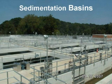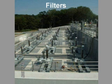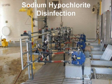This is one of the treatment facilities, the 85 MGD facility. It is not online yet. Both of the treatment facilities, the one on the east side and the west side, are about the same. They include drum screenings again from the tunnel flow, the flow that's pumped out of the tunnel. Up in the upper right-hand corner, you can see where the pump station is located down the tunnel shaft. It is pumped through drum screens, then it goes through vortex separators to get out